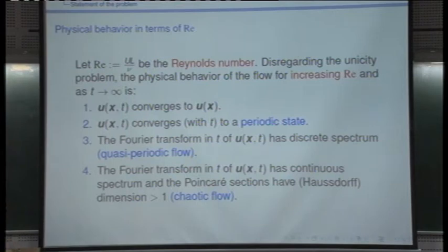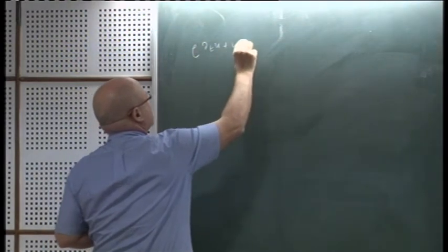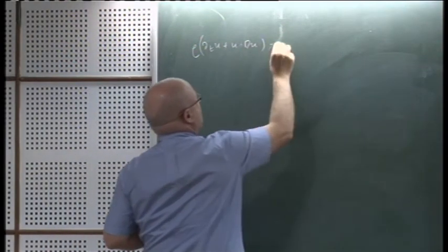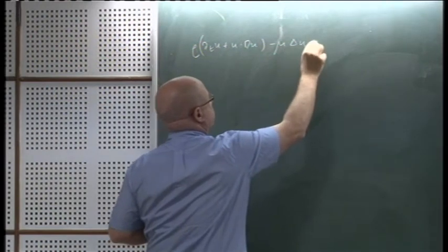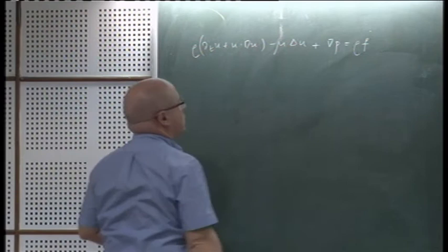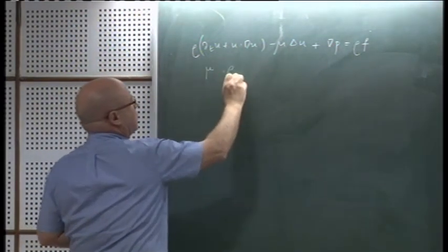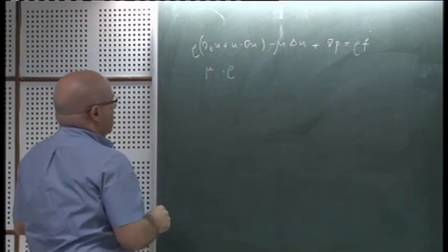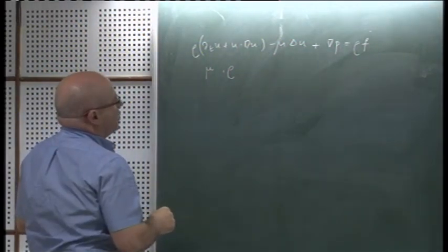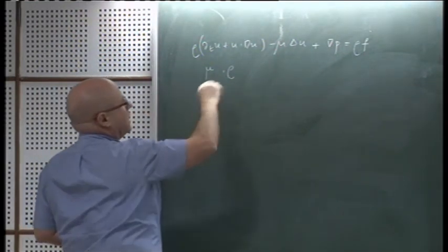I mean, that comes from making the equations dimensionless. I mentioned in the beginning that the original equations, when obtained from continuum mechanics, are those. Those are the equations obtained from continuum mechanics, where mu is the dynamical viscosity and rho is the density, okay? So the point is that you can make these equations dimensionless. Well, first you can divide by the density everywhere.